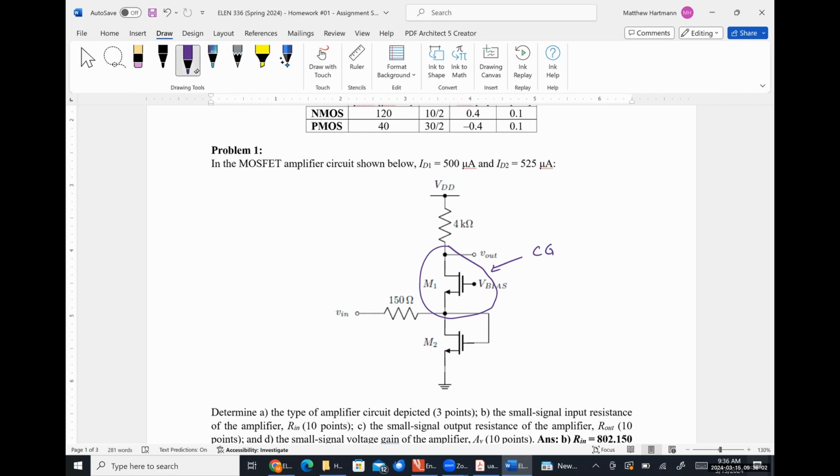Okay. Then we have this part down here. What is that? Well, that is a diode connected NMOS transistor, which means it's going to look like R naught in parallel with 1 over gm, right? This is playing the role of the emitter resistance. So whenever you have a common gate amplifier, you literally just replace RE with this guy right here and use the relationships that we developed last quarter. It doesn't have to be harder than that because that's literally all you need to do.